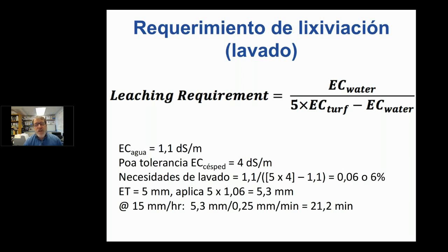Now, we noticed in the Los Angeles example that the sodium levels in areas that received higher precipitation of 250 millimeters, or I can't remember now. Let me see what the precip rate was. If they had a precip rate of 66 millimeters per hour, which is a pretty high precipitation rate, that was in the center of the green when there were 4 irrigation heads hitting the center of the green. With that high precipitation rate, the salts did not accumulate. So they're putting on more water than was needed to manage the salts.